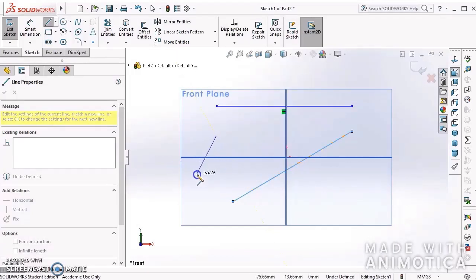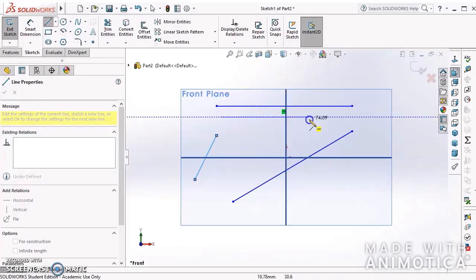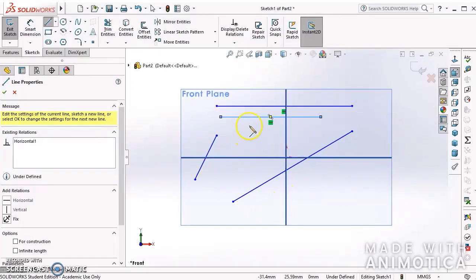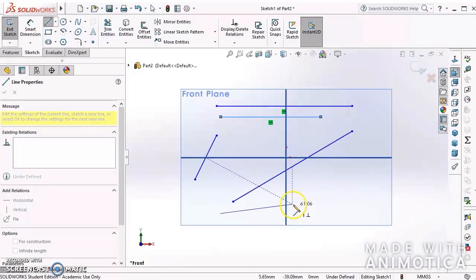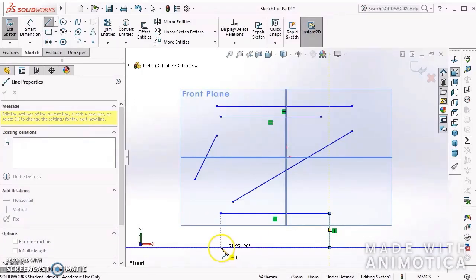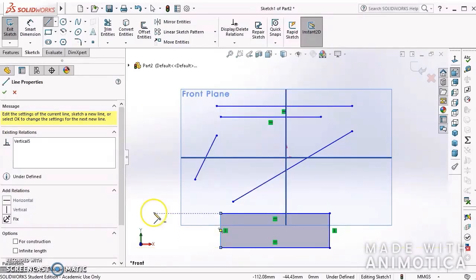Now, the point of click, hold, and drag is that you have only one line. So, click, drag, let go. This is one line. The other way is to click and let it go without dragging, and then you create your part. It keeps making lines one after another until you come back to the beginning, which ends the chain of lines. It doesn't end the command, it ends the chain.